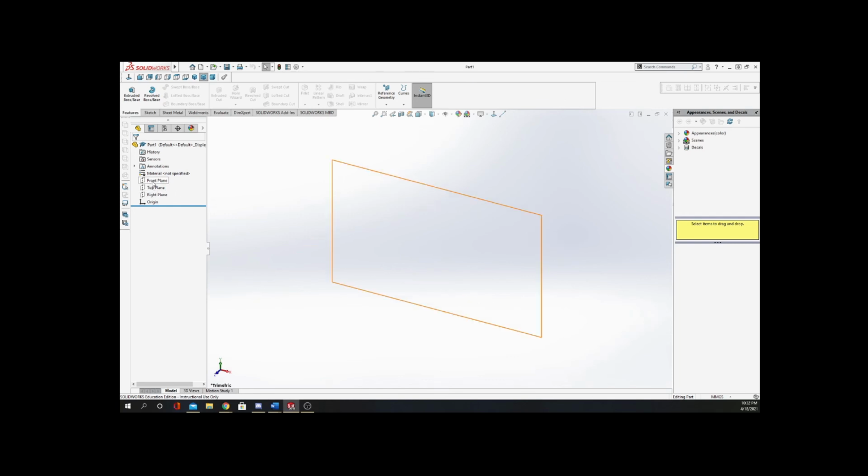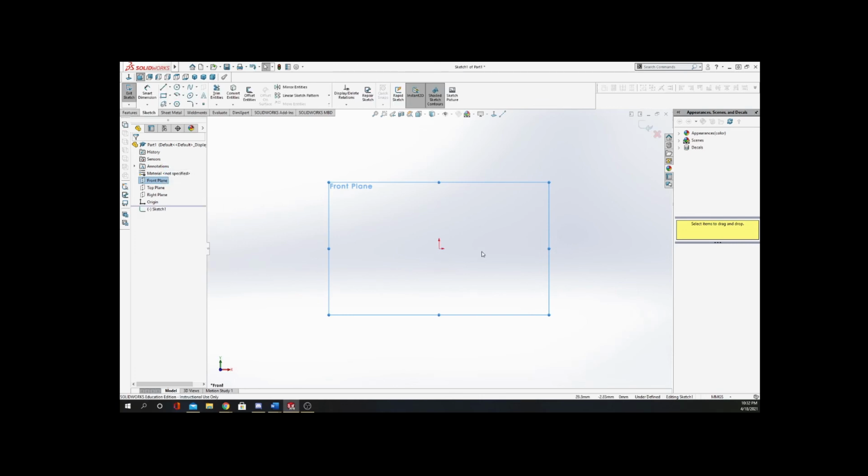You see it over here on the side. You right click on that, and we want to go normal to our front plane. That turns it so that it's parallel to the screen. Right click on it again and start sketching. When we did that, it puts in an origin for us. That's this spot right here, and this is basically a known location in our drawing tablet.